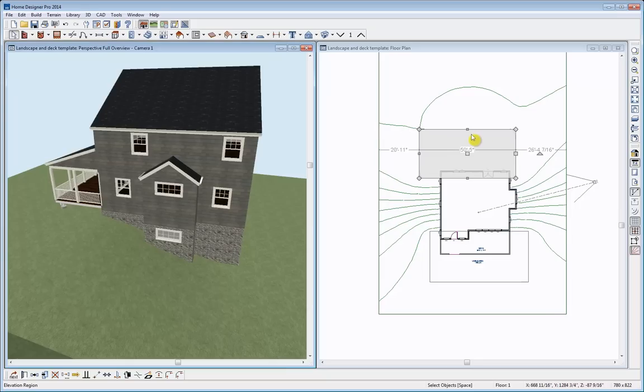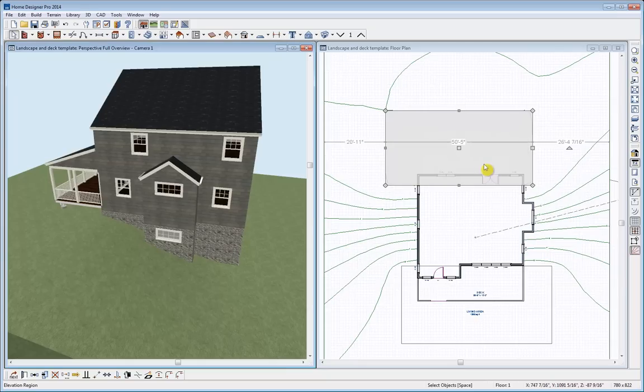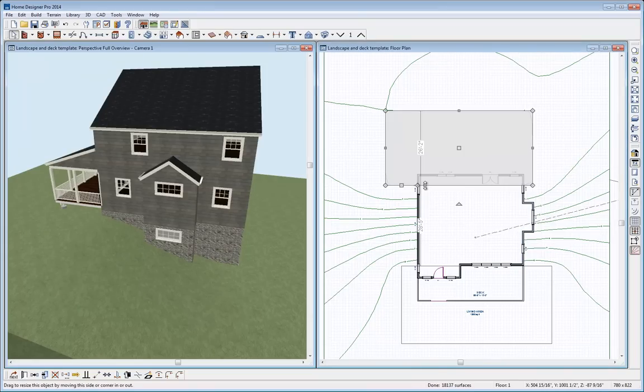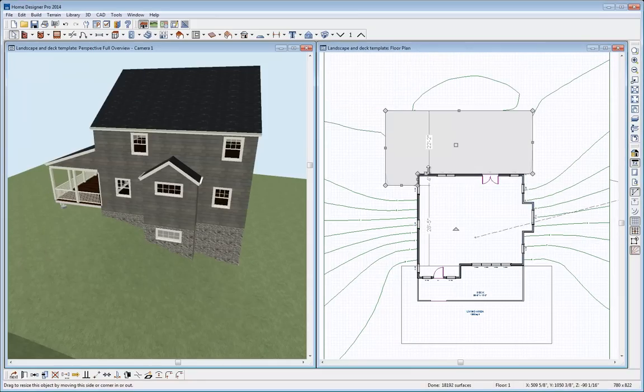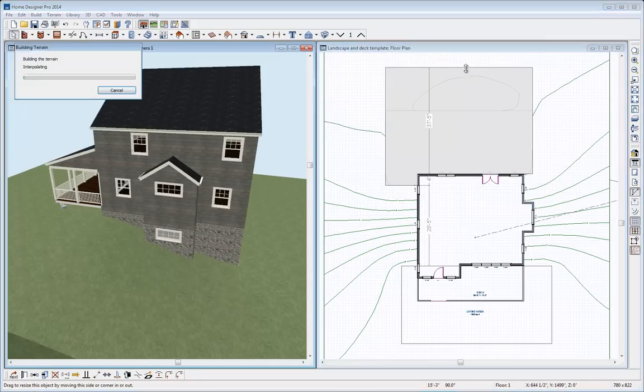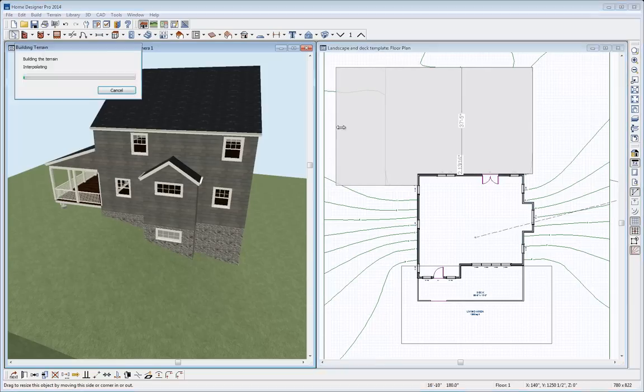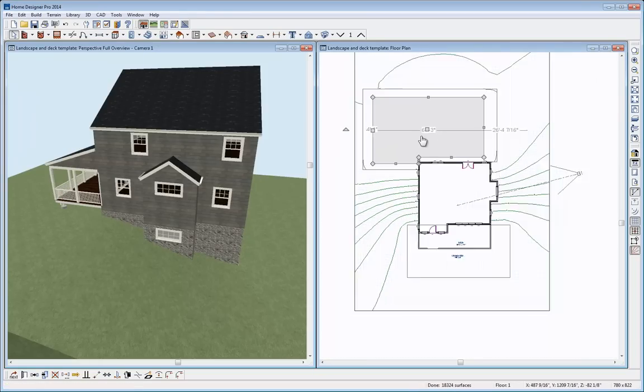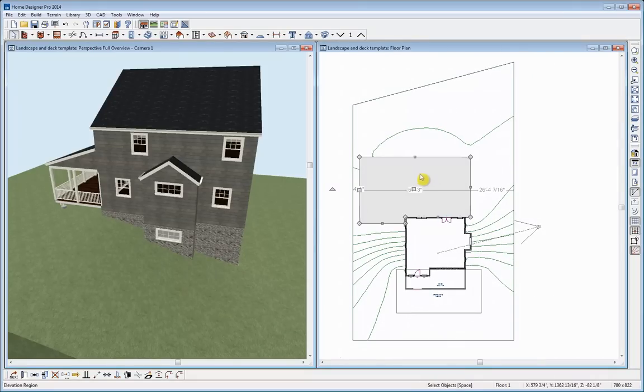Now we also can edit these regions. So I'm going to zoom in just a little bit, and I'm going to go ahead and use this break line tool. With that region selected, this again is my edit toolbar to edit that particular object. So I'll simply break the line, and that enables me to pull just a section of it back. And I think I need this to be a little bit larger too, so we'll use our edit handles to resize that.